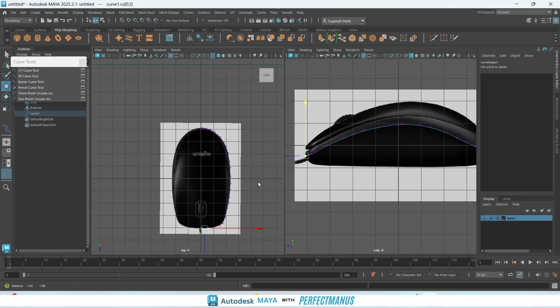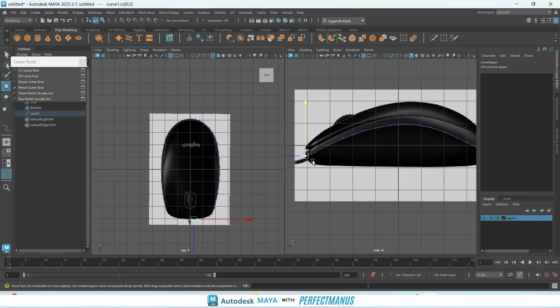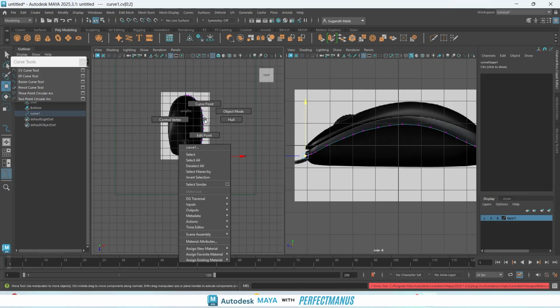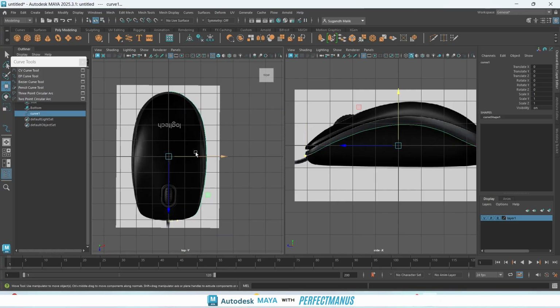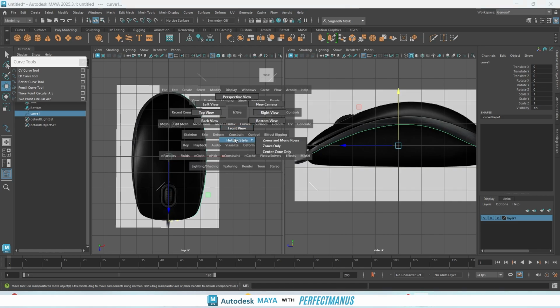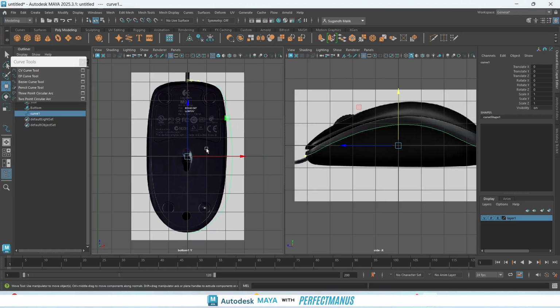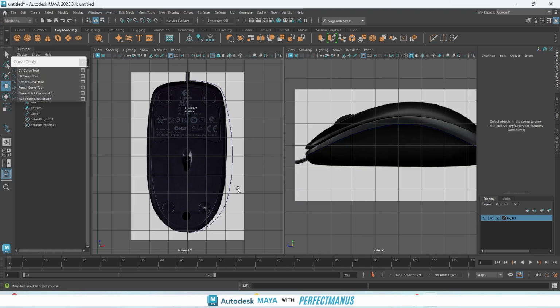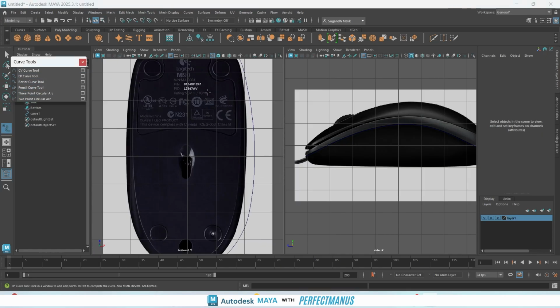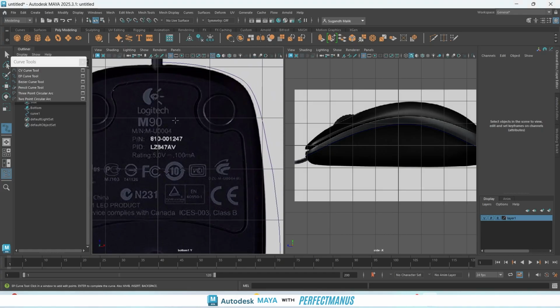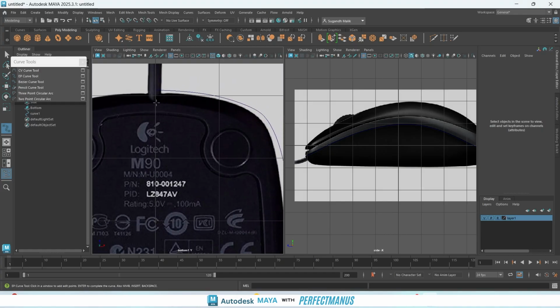Now you need to follow your bottom view or your top view. So we are working on this part right now. We'll be simply focusing on this one. But now instead of your top view, we'll be moving on to your bottom view. So again, your space bar and your right click hold bottom view. You don't need these parts. See here, you'll see those areas outside because of the camera view perspective. Again, the same thing we'll be doing. We're following these lines.